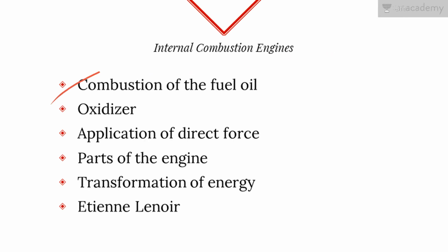An internal combustion engine is a type of heat engine where the combustion of the fuel occurs with an oxidizer in a combustion chamber that is an integral part of the working fluid circuit. In the engine, the expansion of high temperature and high pressure gases produced by combustion applies direct force to some component of the engine. The force is applied typically to pistons, turbine blades, a rotor or a nozzle. So those are the parts of the engine. This force moves the component over a distance, transforming chemical energy into useful mechanical energy. The first commercially successful IC engine was created by Etienne Lenoir around 1859.